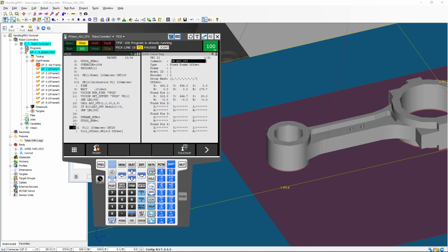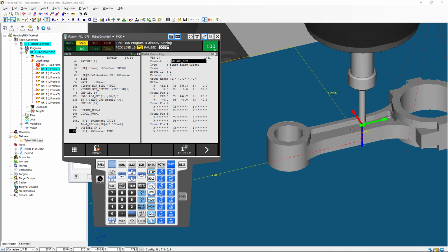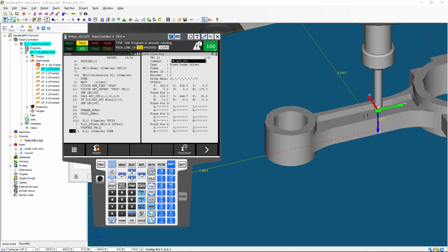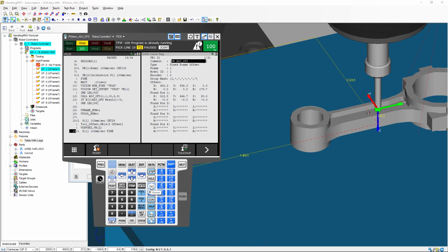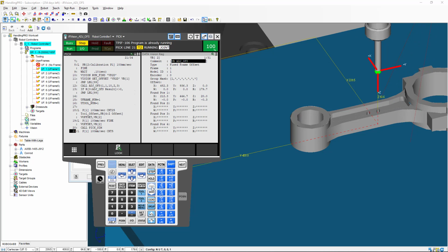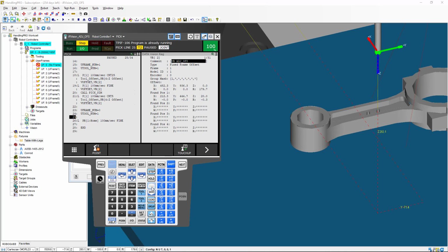We're going to go to the touch position. And you can notice that we are dead center on the touch position. So with this position register number 10, we were able to correct the offset that we had originally. We're going to keep running the program, and go back to the beginning again.